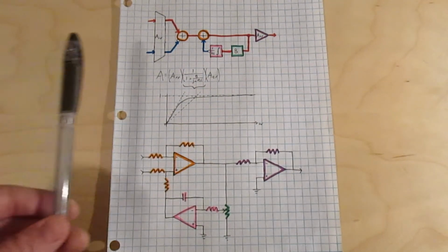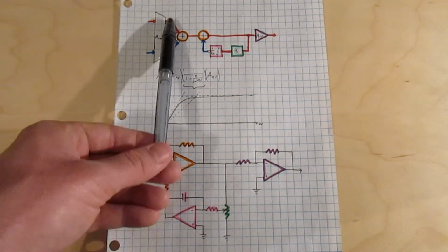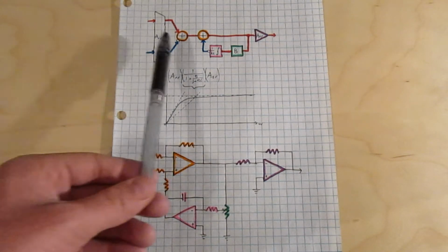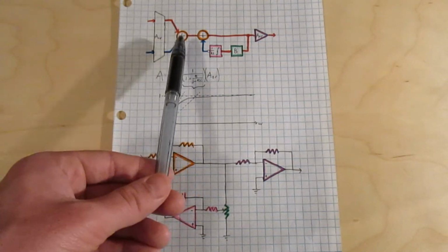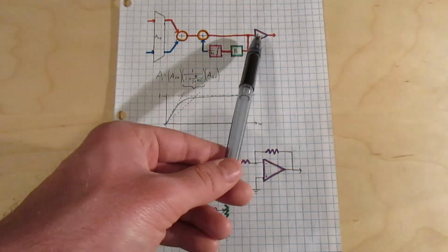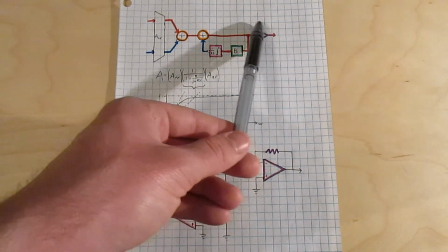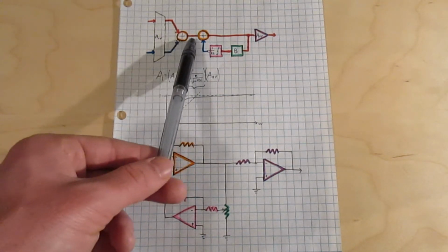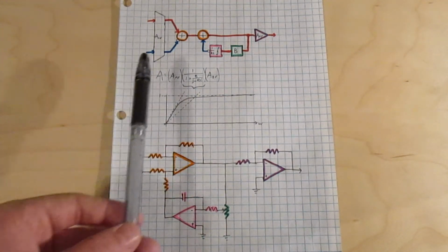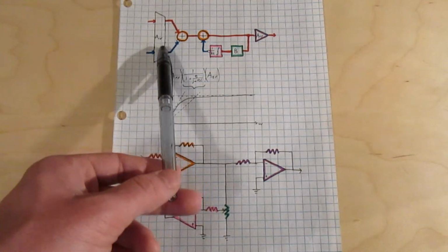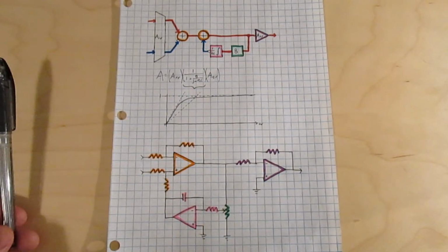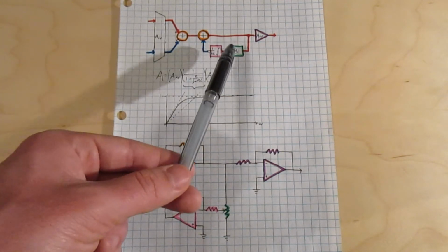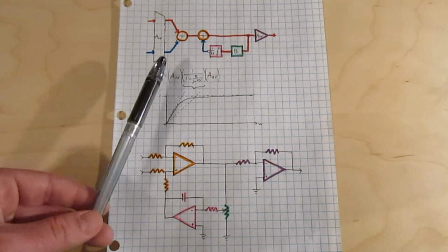I originally wanted to put the DC offset tracking in the differential part of the circuit just so that I could have a gain of larger than 1 at the back end, because then the back end wouldn't be seeing any of the DC offset. This way I'm going to have to spend an extra op-amp making another amplifier on the end of everything else. But because this adder is built into the back end of the in-amp, I don't have to spend another op-amp as an adder in between the front end and back end of the in-amp. So in the end it has the same number of op-amps, it doesn't reduce the common mode rejection, and gives me a knob I can turn to adjust the corner frequency.